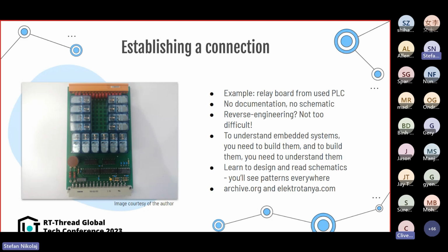In this section, I will share my experience with reverse engineering and finding information to interface with legacy systems. I'll take the example of this relay board in the picture, which I took from a discarded industrial PLC, which I mentioned in the beginning, whose processor board had failed. The most challenging part of connecting this relay board to the microcontroller was the lack of information about its operations, schematics, and connector pinout. However, because the hardware was relatively simple and the board was connected to a Z80 microprocessor bus, reverse engineering it wasn't too difficult.